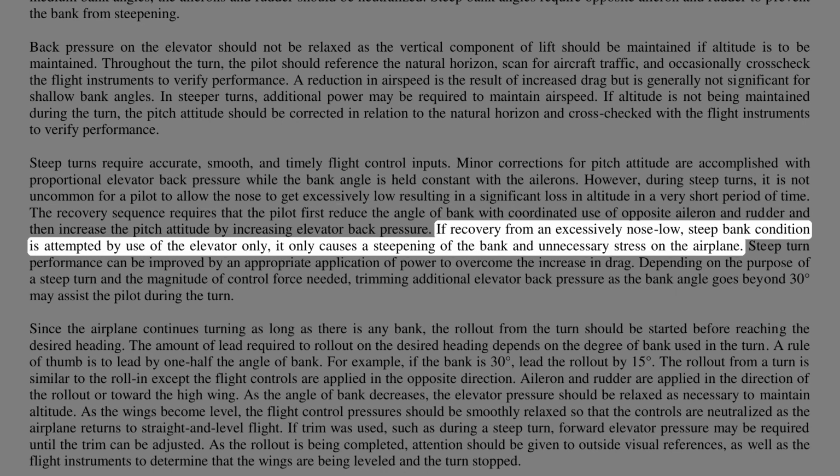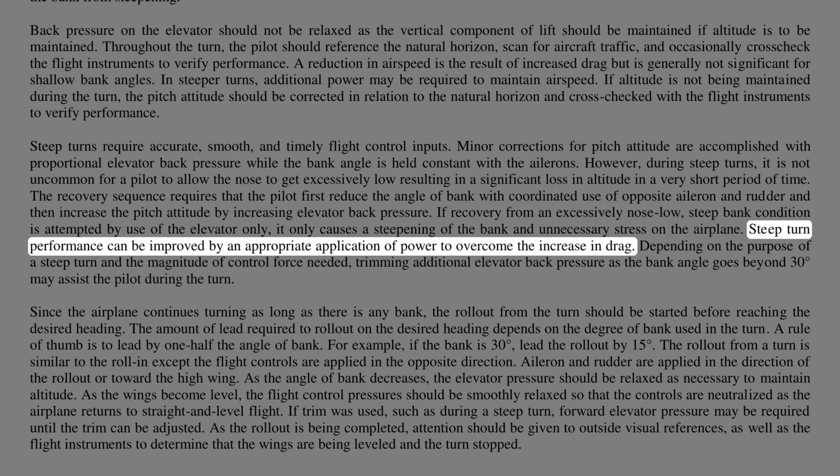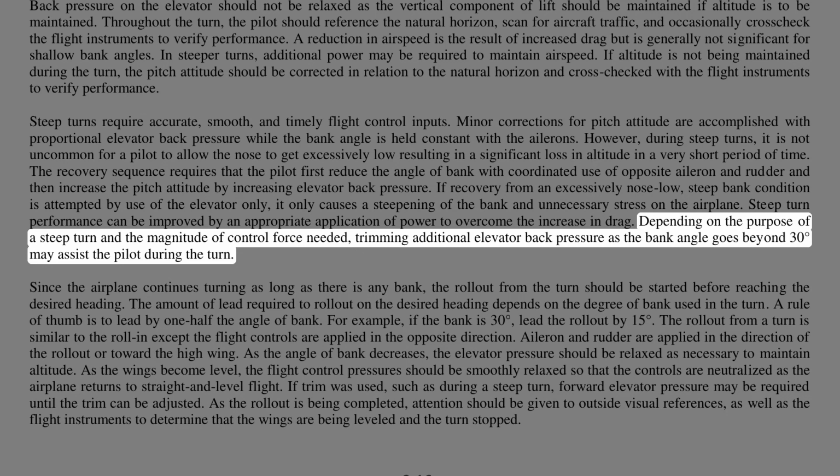If recovery from an excessively nose-low, steep bank condition is attempted by use of the elevator only, it only causes a steepening of the bank and unnecessary stress on the airplane. Steep turn performance can be improved by an appropriate application of power to overcome the increase in drag. Depending on the purpose of a steep turn and the magnitude of control force needed, trimming additional elevator back pressure as the bank angle goes beyond 30 degrees may assist the pilot during the turn.